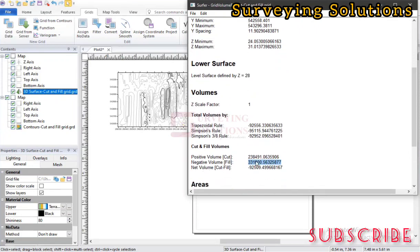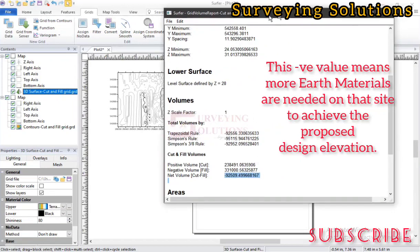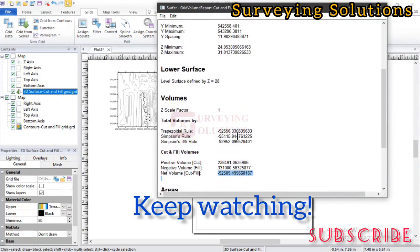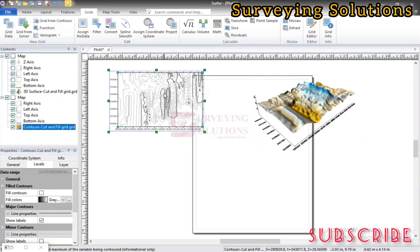Then this is the net volume, that is cut minus fill. Having subtracted both from each other, you have this as the remnant. Are we together? Good. So this is how you carry out, or determine, the cut and fill analysis of any terrain. However, that's not the end. We are still going to look at how you can see these in a better perspective, or let's say how we can display this in a better perspective.